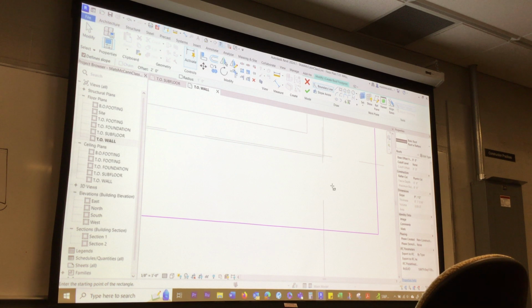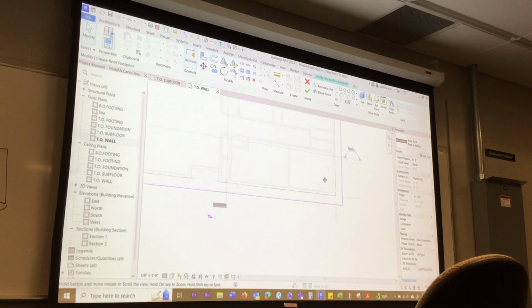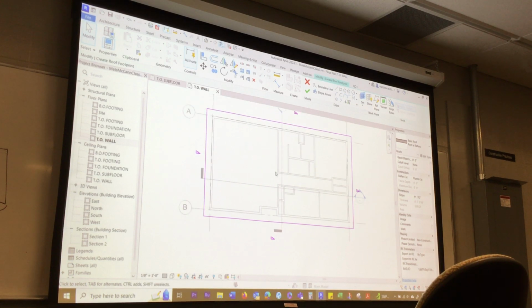So I'm just gonna hit escape. I still got my drawing tool. I'm gonna hit escape again. I don't need my drawing tool. And I'm gonna look at it. Cool. Now, I can come over here and I can change the slope. It's at 912 right now, which would look ridiculous. We're gonna go 412, because that's what the DWG, if we went and looked at it, would say.